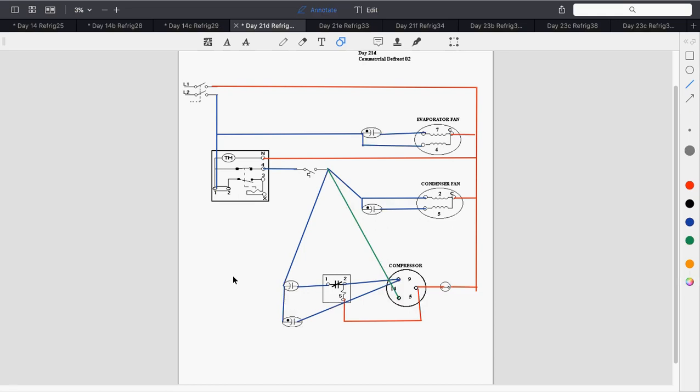Now, where you see these is in what we call medium temperature units. It's the borderline between medium and low temperature. Our product is as close to freezing as we can get it. For example, I have a product at 32 degrees, which means my evaporator coil is running under freezing. So my box temp might be right above freezing. When this comes on, my evaporator is running under freezing, but I know my box temp is never going to be cold enough that I can't just turn it off and circulate air across it and defrost it.